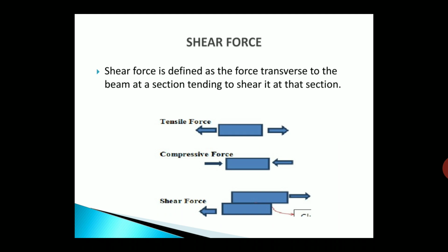When we see the tensile force, we observe that the forces acting on both sides are trying to pull the element, whereas in case of compressive force, the forces are trying to compress or push the element, whereas when we see the shear force, both forces are acting in opposite directions, which leads to the shearing of the surface. Now, understanding the design of shear force is not as easy as the design of a flexural element.